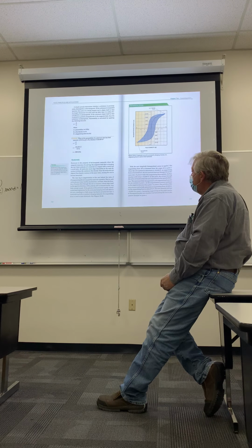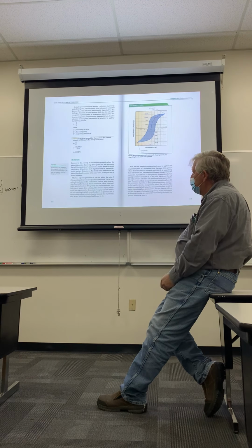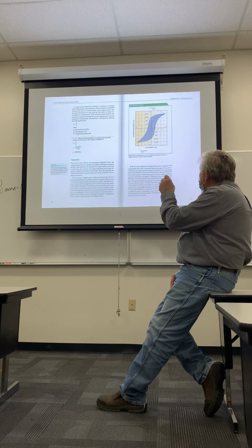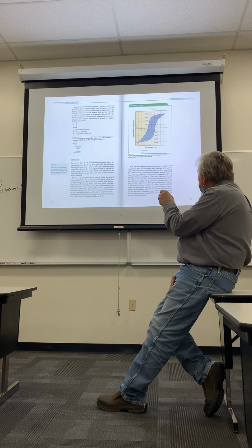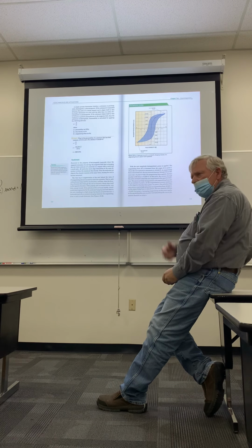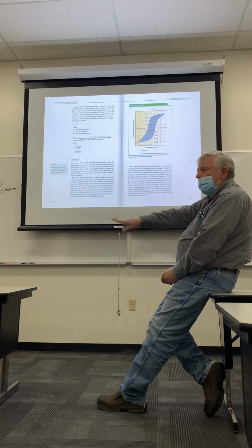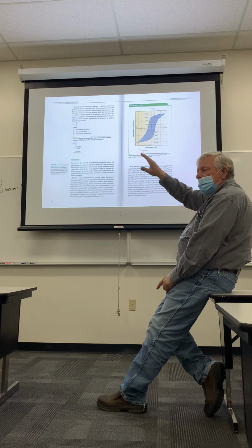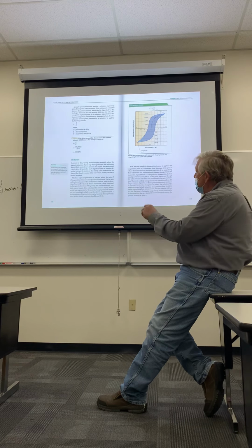And when we turn that off, there is a bit of lag in time, in seconds, before it is completely demagnetized, and then actually goes into a negative. Right down here it says, as magnetizing force is decreased to 0, the core material does not demagnetize at the same rate. Makes sense, right? You energize it, it ramps up. You demagnetize it, it ramps down. But it takes a little bit of time and it lags behind. That's what hysteresis is.